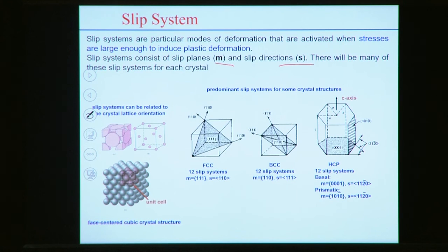And then with the regular arrangement of the atoms, we can represent that one repetitive representation of the characteristic of the geometric arrangement of the atoms, that is represented by the unit cell here. Now within the unit cell, this is the first figure. If we look into that FCC structure, and we have discussed that FCC structure, the slip plane and corresponding slip direction are defined. So a total of 12 slip systems is possible.